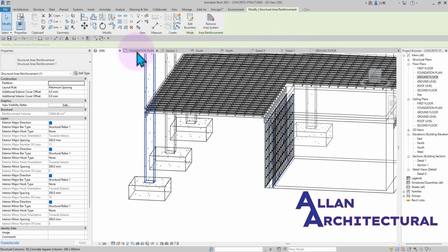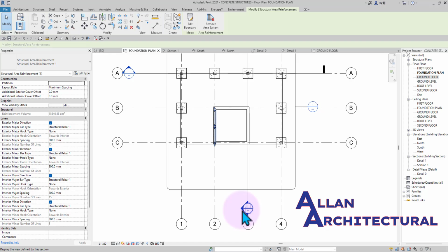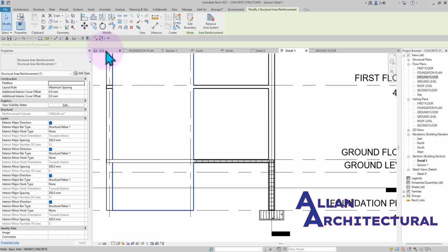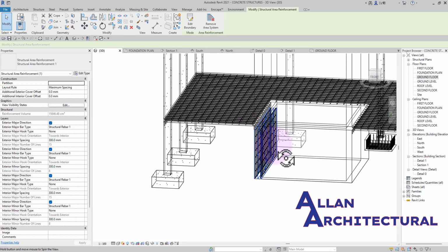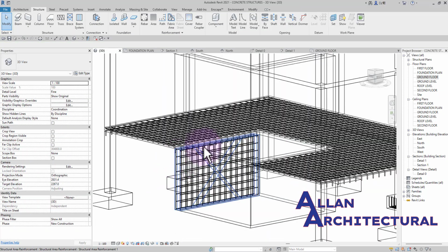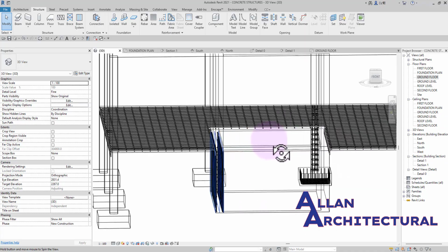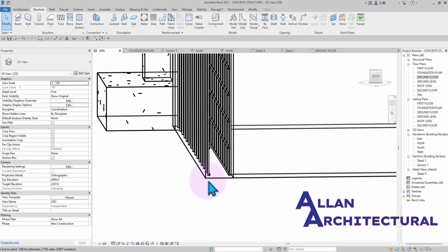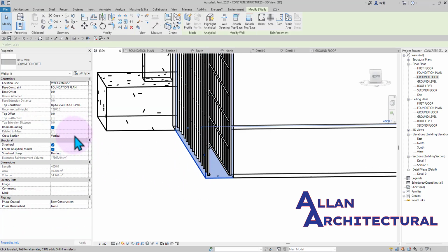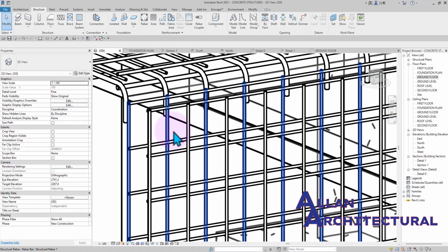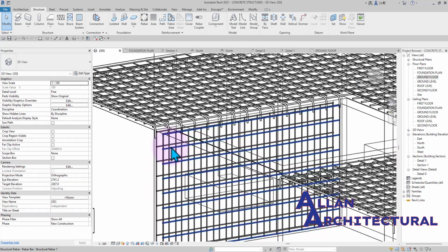Let me get back into that section view. I can't see that in this view, so I can go back into the 3D view, pan around a little bit, and click on that dot to move this up a little bit so it hooks with that in there. You'll notice the rebar cover is very close, so you can change the rebar cover at any point in time you want. This is how you can model all of those rebars inside of the software.